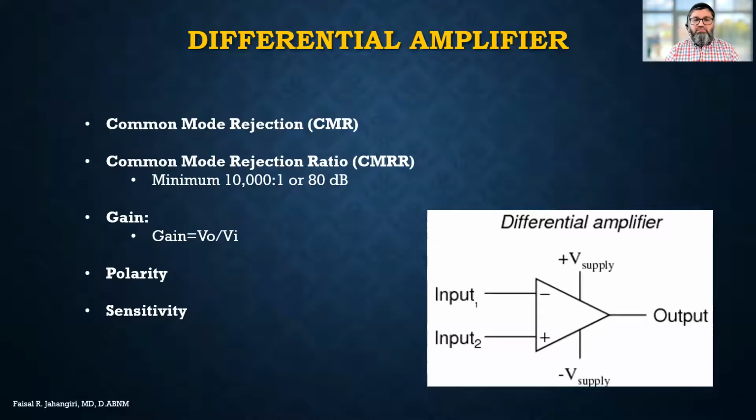We cannot trust them. The reason the two will cancel out is that, as we talked about, the first input is a negative input and the second is a positive input. So the signal is not A minus B. Input 1 is A and input 2 is B, so the formula we use is minus A plus B. It is always an addition of inputs 1 and 2, but before we add the two, input A becomes inverted.